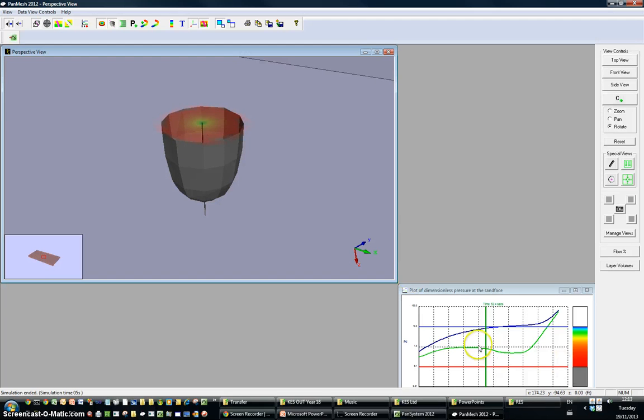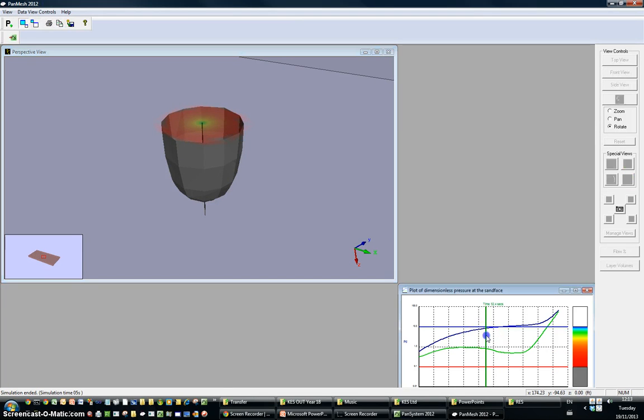Now we started out, we have a wellbore which is a 50% completion length. So you can see it begins at very early time here. The pressure response moves out. So we can see this little bump on the derivative in the response curve corresponds to the partial completion.